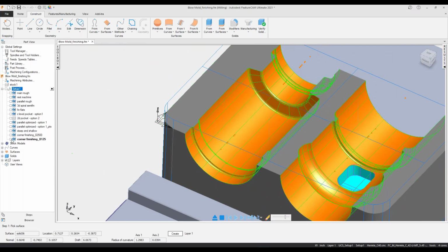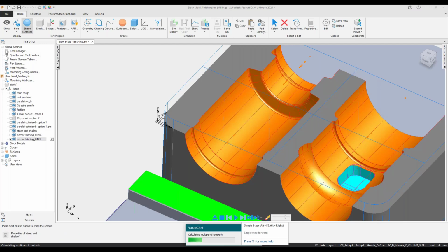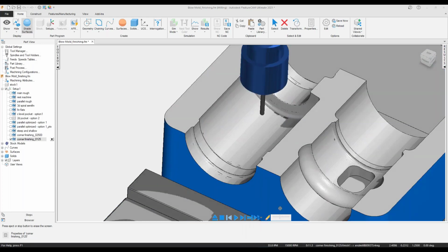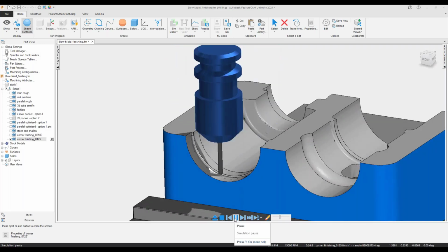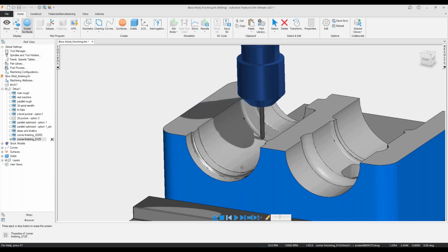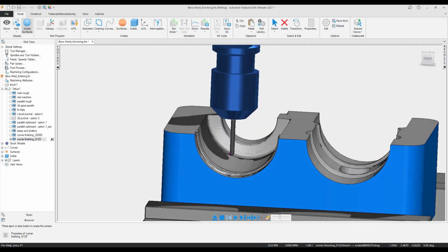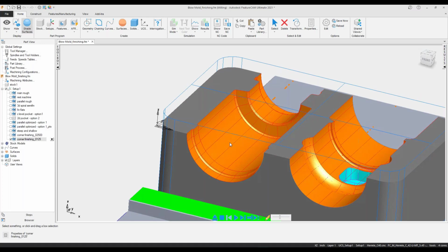So let's go ahead and take a look at this last toolpath, which is the same toolpath we just looked at, with a smaller tool. I'm just going to go ahead and run the 3D sim once again to step this through. Okay, so we can see the tool. If we hit play, there's the smaller tool getting that stock out. Now, if we pause, let's play that through again. We can see that maybe the tool is having some issues here because of the reach. Looks like we've got a gouge. So this is where, let's eject. We want to keep that tool nice and short.